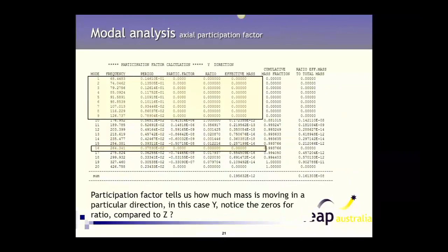Okay, so if we apply the step excitation in the axial direction, you have to have quite small time steps to capture that response, even in an undamped solution. Because we're using tiny time steps, your solve time is going to be significant. So this is why you'd never jump straight into a transient simulation without first understanding the modal behaviour of your structure.